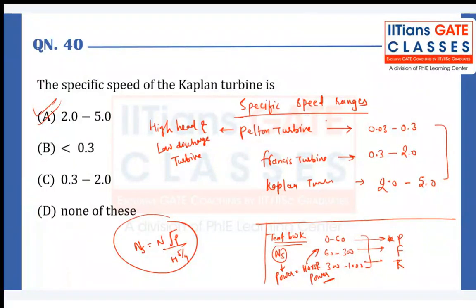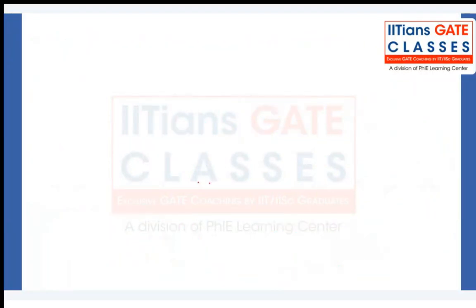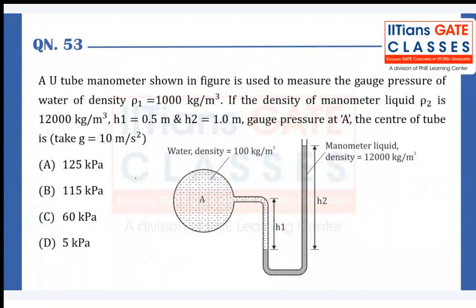Now, all of you might have understood what I was talking about. Try to see this question and try to solve. Apply the manometer equation at the lowest level. The lowest level I'm considering here is at point P and point Q. Pressure at point P has to be equated to pressure at point Q.